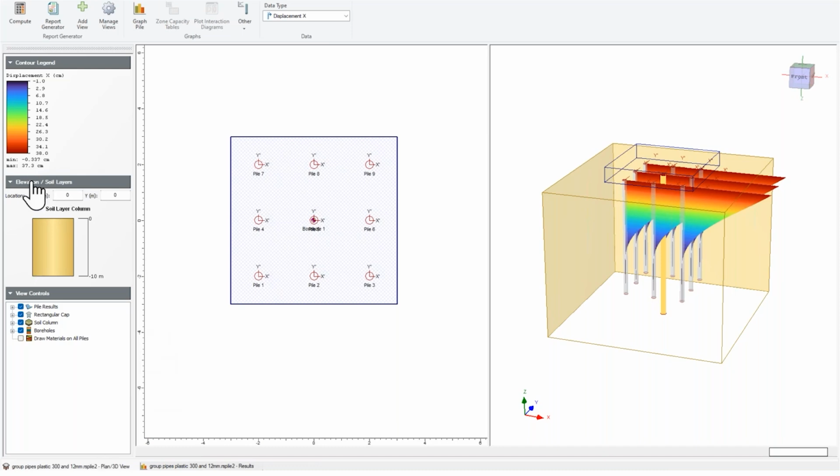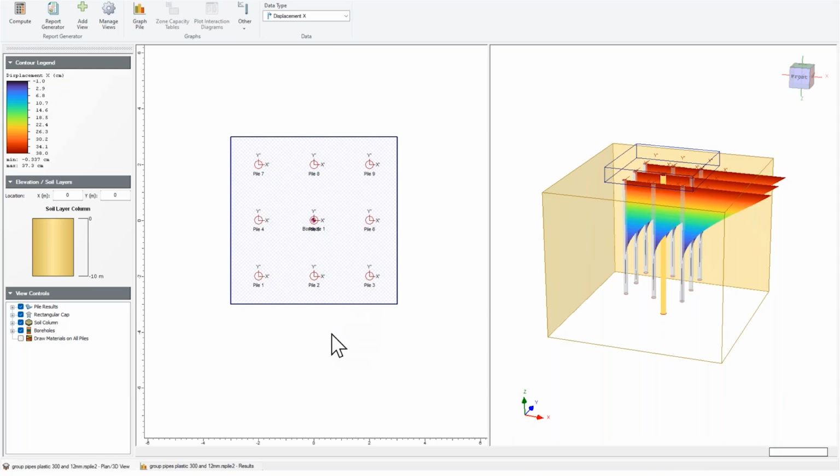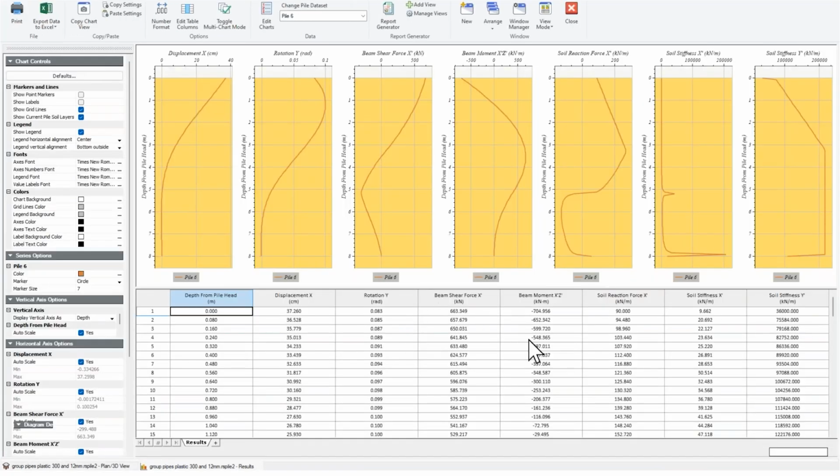This is 70. It's still high because the pipe is small. This is made for demonstration so that you can feel the values. The first one was reaching 160 centimeters or something. And when you go to the analysis, you will still find the maximum moment. Here it's around 700 in the beginning, then goes back again to around 660. Of course, because it is stiffer, it will get more moment now, right? So we're talking about 670, almost the maximum.